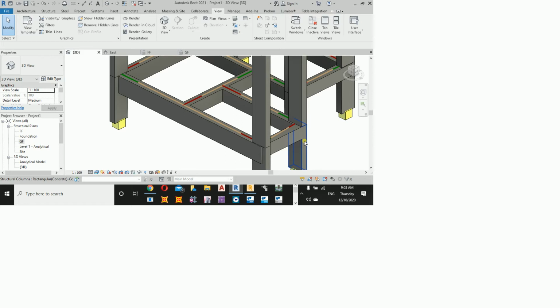The other thing, now if a person told me I want to do the rotation not in Robot, I want to do the rotation of the column or orientation of the column in Revit. You can do the modeling in Robot. It's easier in terms of accuracy. If you model the slabs in Revit, they are not going to be fully 100% correct when you transfer to any other software, even if it's Robot. So normally I recommend if the structure is easy, you draw everything in Robot.